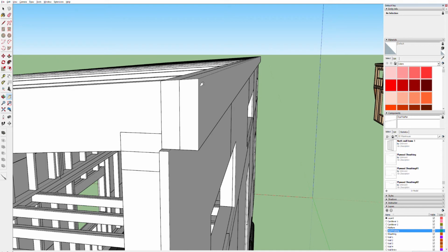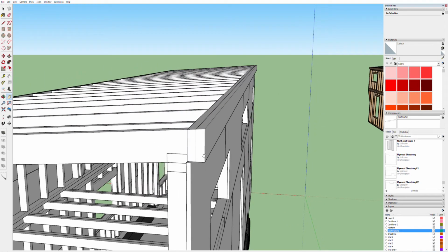So the idea is that water that sheds off the back end of the roof here is going to, well, not much is going to shed off the back end of the roof because the pitch is going the other way. But the point is that water coming off that flare is going to drip out away from the house. If it does hit the house, it'll hit the outside of the siding and then drip down the outside of the house until it drips off to the ground.